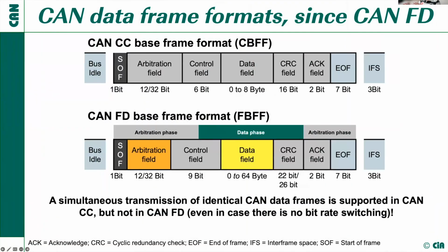And now, when it came to CAN-FD, we said, wow, great. We now have 64 bytes of data. Now there must be some possibilities for improvements for the LSS as well, to accelerate it. And then we were double checking and we said, yes, in theory this would be great, but we need from time to time also that several devices communicate the same frame at the same time.